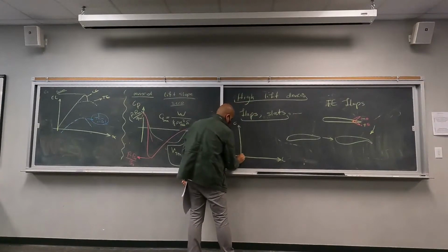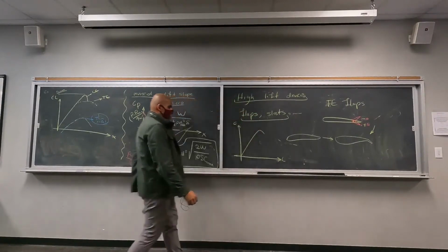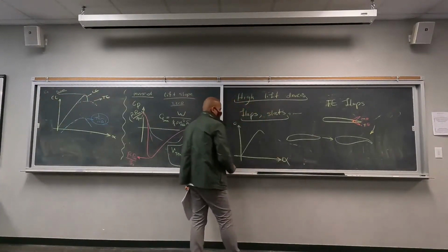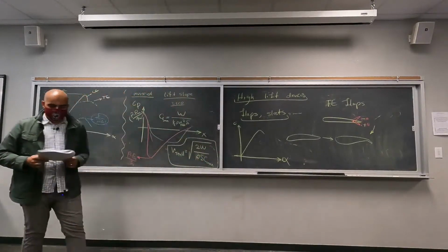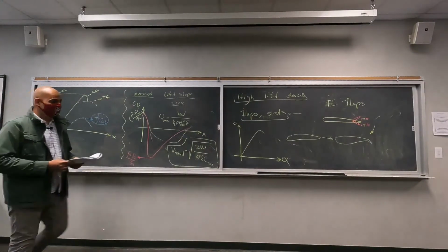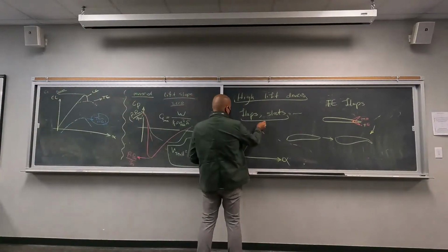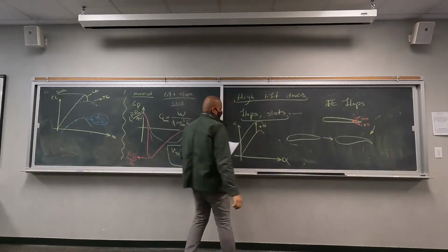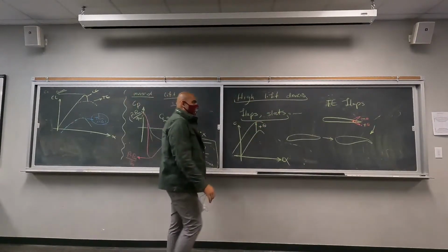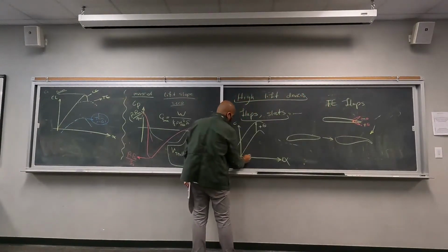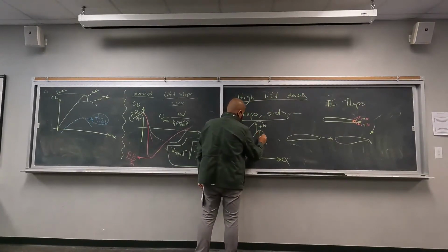Let's say this is the symmetrical airfoil. So we start at 0, and this is CL versus alpha. What will happen with a positive angle, which essentially means that we are increasing the camber, right? Your CL, your maximum CL, is going to be higher, right? So positive theta. And if you move this trailing edge flap in the other direction, your maximum is going to change.